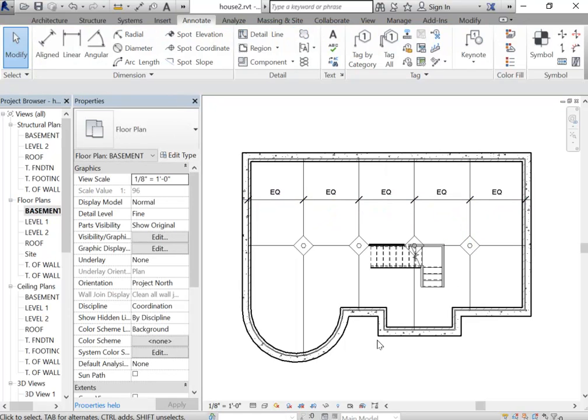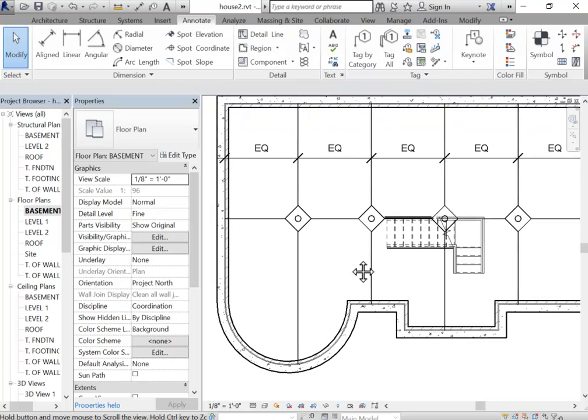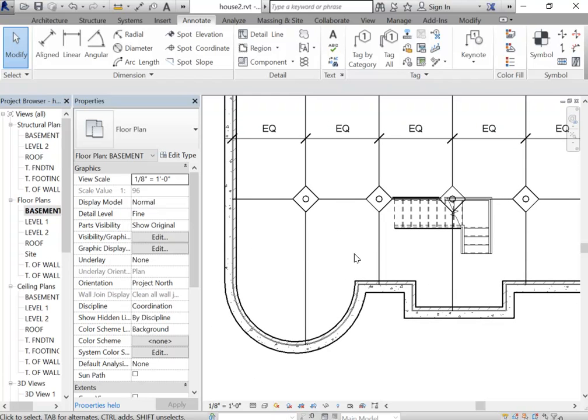The next thing I want to do is look at my problem areas, and basically what I really want to do with these control joints is section the concrete up into individual squares or rectangles, shapes that aren't going to easily crack. And this area right here is jumping out at me as a potential problem area. Right here, this is a place where a crack could occur.